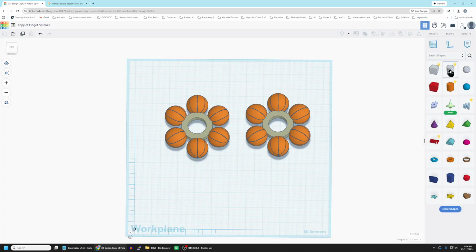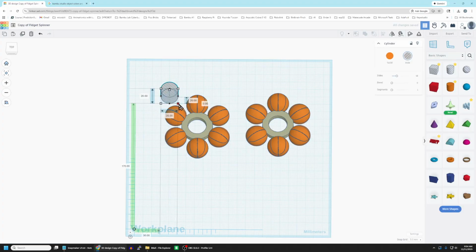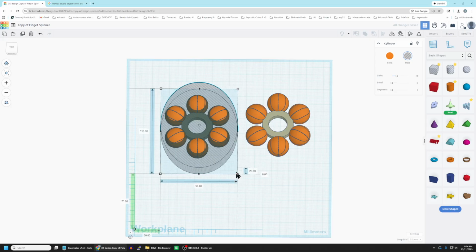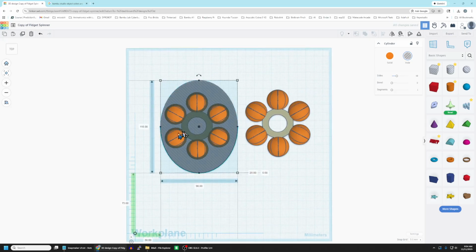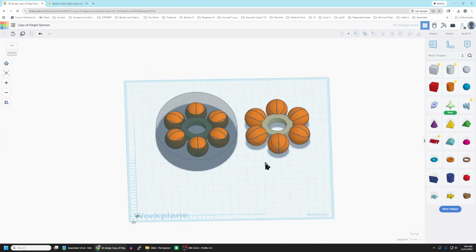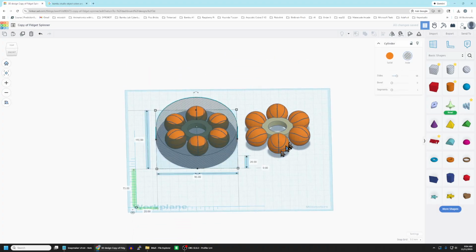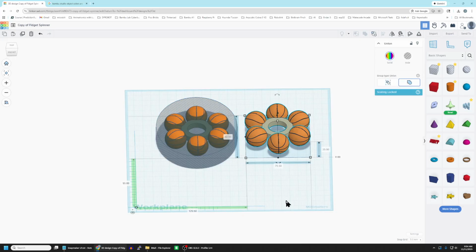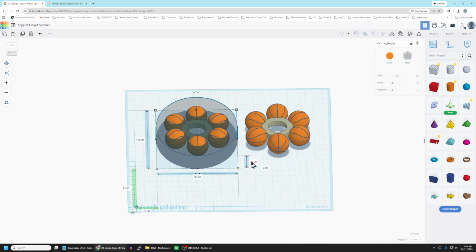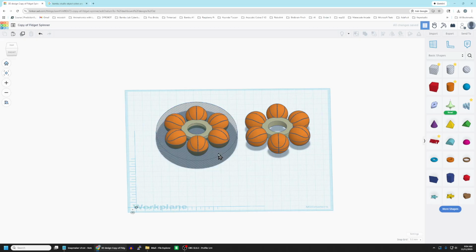And I'm going to bring out a cylinder. I'm going to make it nice and big so that when I look down, I can see that it's the size. It'll do everything in there. This whole object is 25 millimeters high. I'm going to make this 12 and 1/2 millimeters high. 12.5, half of 25, okay? That's lovely. I'm going to duplicate it.